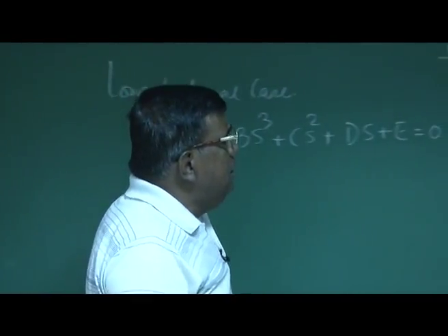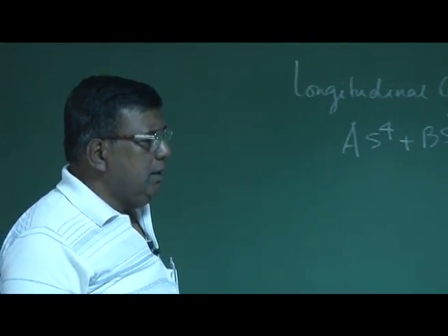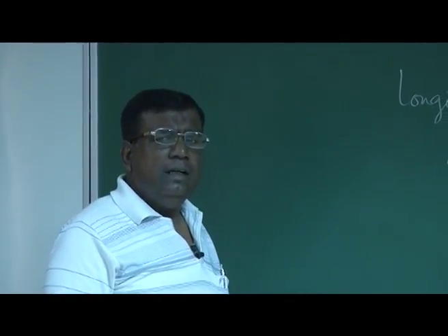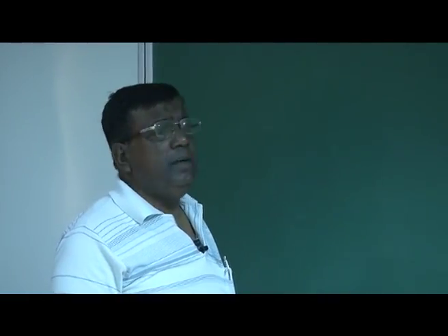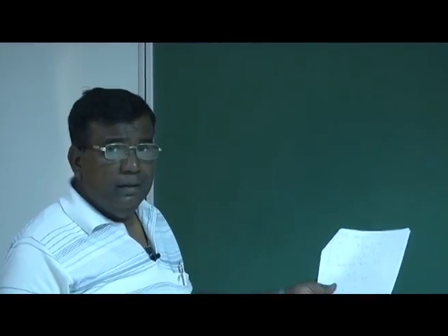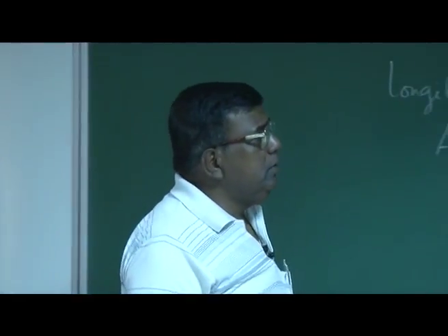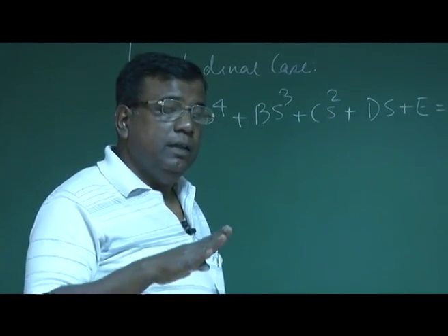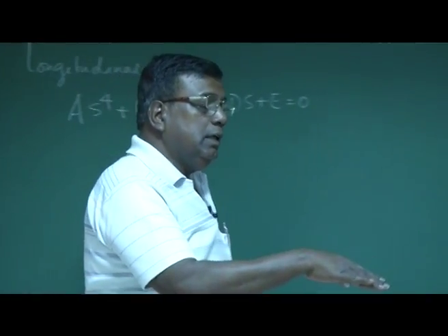The second root had a much smaller negative real value, suggesting a long period mode, unlike the short period mode where the real root was large negative, around -1 for the sample case. This long period mode we realize is the phugoid mode, that is, after a disturbance, the airplane can get excited like this, okay?